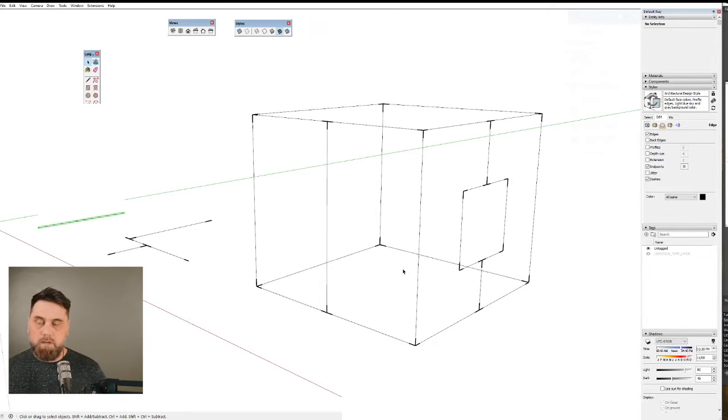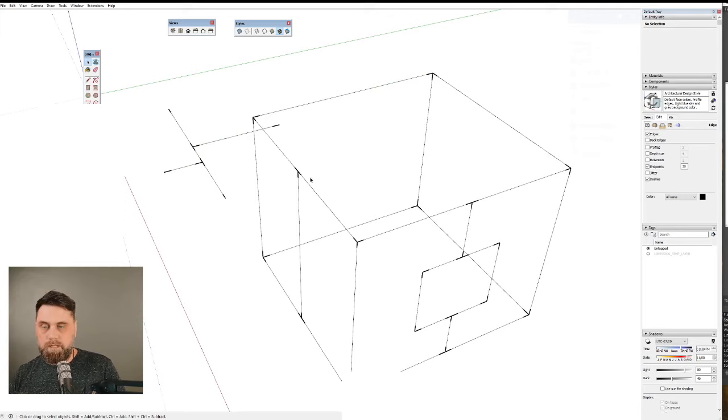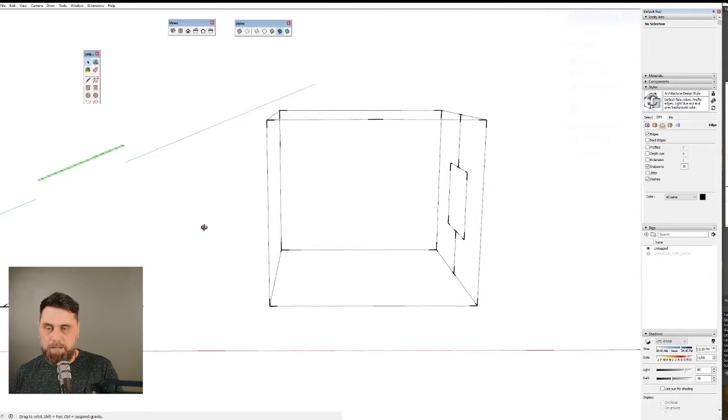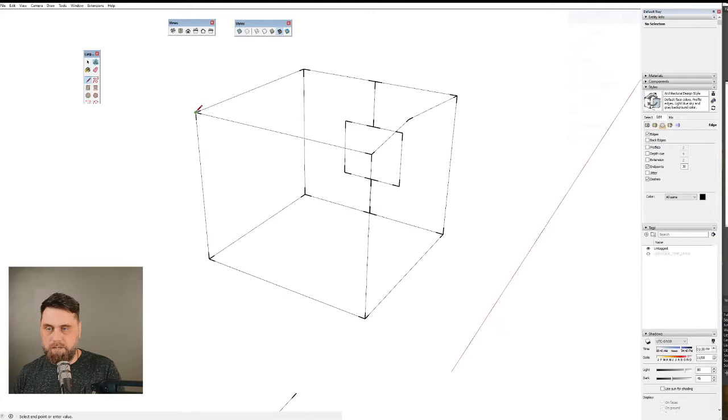All right. So there needs to be a specific set of things that are a checklist, right? So it needs to pass a test in order for SketchUp to create a face. So if we would, let me move this back a little bit and delete this edge. All right, so if I was looking at this, and let's go over here. We wanted to create a face right here, and we need to first complete a circuit. So that's the first thing, right?